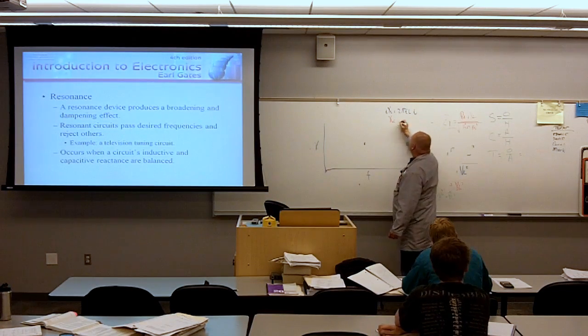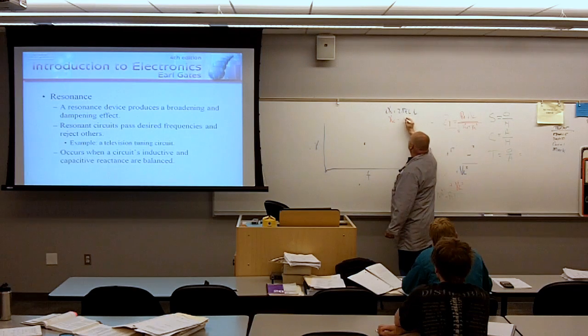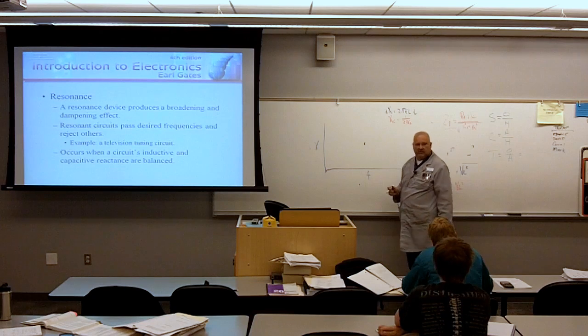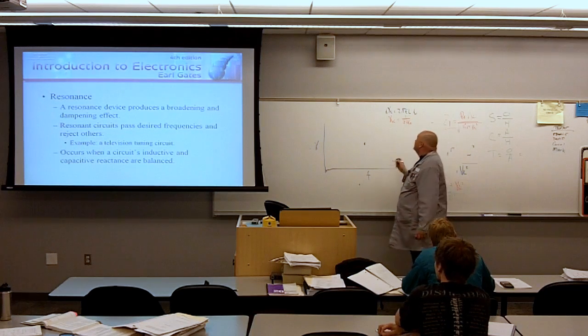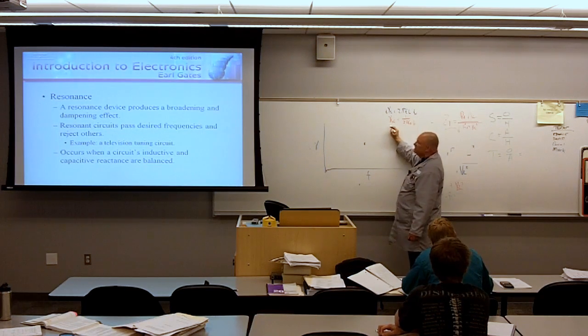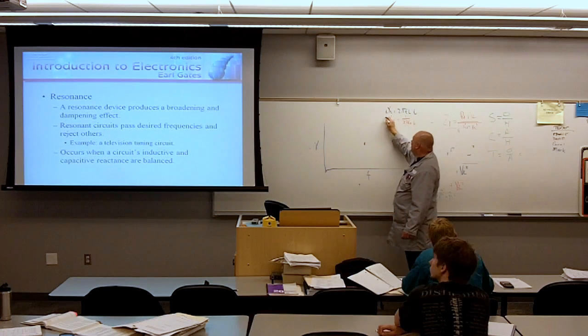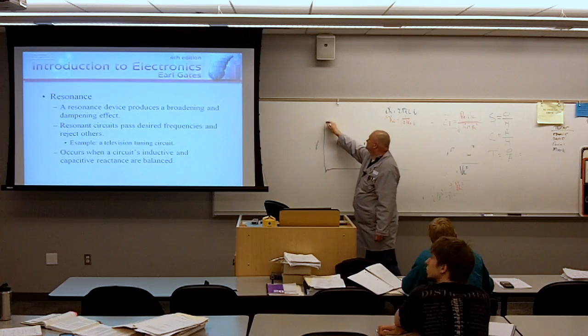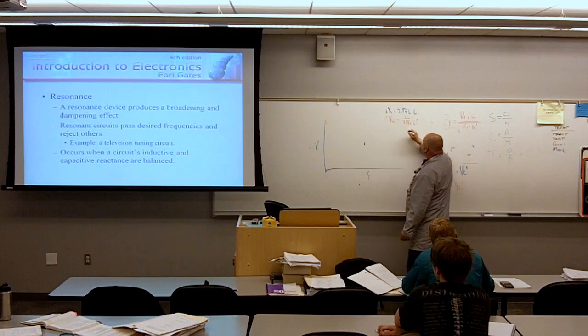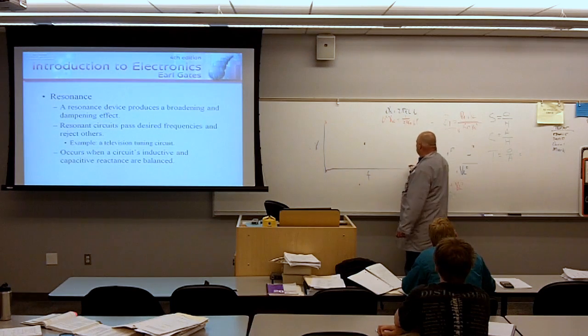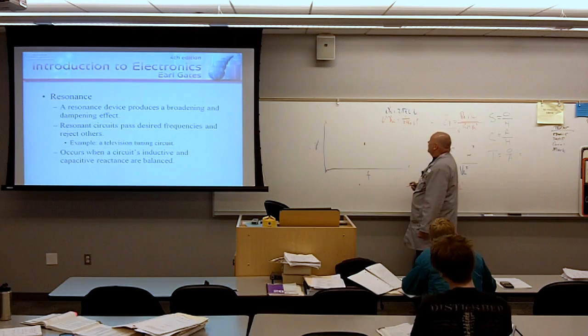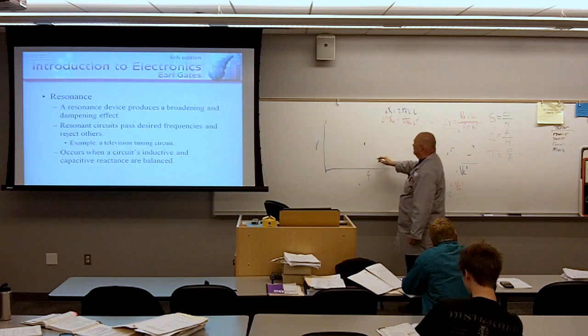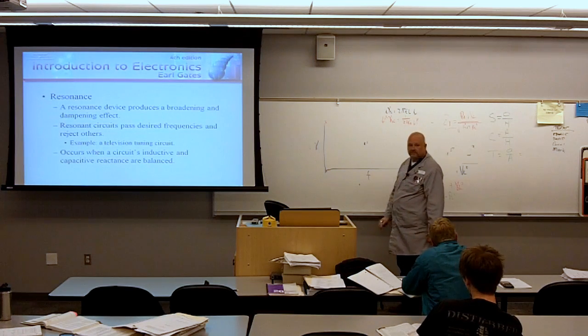X sub C is equal to 1 over 2 pi FC. Do you agree with that? So when I'm at a low frequency, my X sub C is going to be high. When I'm at a high frequency, my X sub C is going to be low. When I'm at a medium frequency, it's going to be medium.